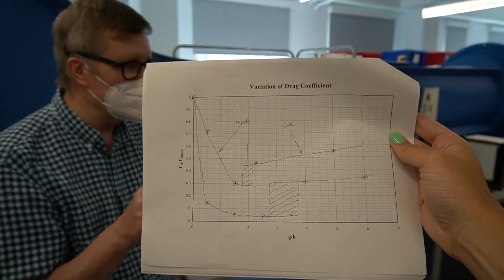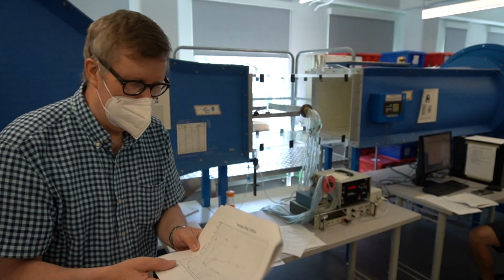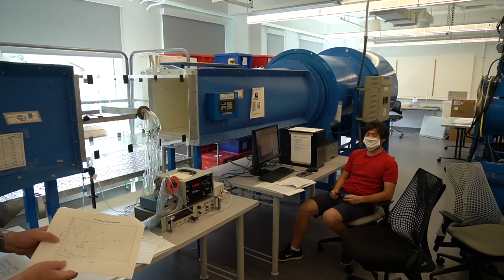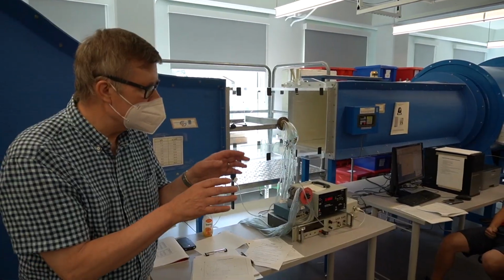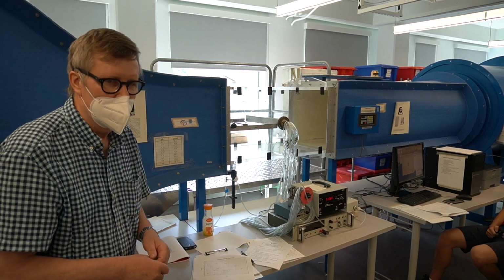But can you remember what the name of the modes were from the lecture, from the pre-lab? Jay, what's the first mode? So the one that results in greater drag reduction is cavity mode. And the other mode, the one that results in lesser drag reduction, is the wake impingement mode. Correct. And so can you physically show people, talk about that for a second?